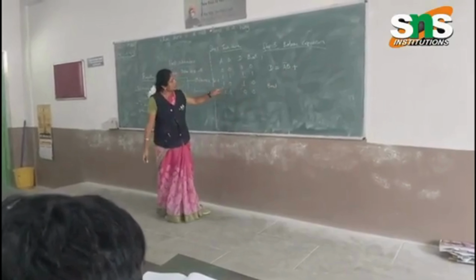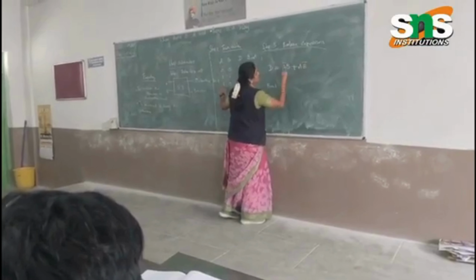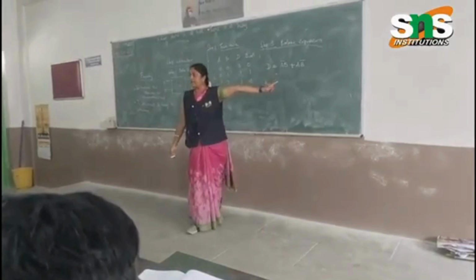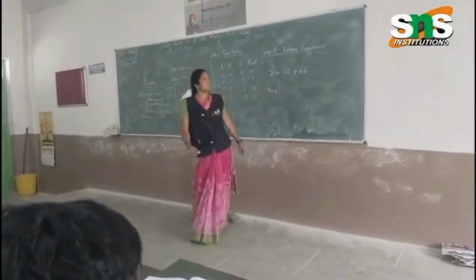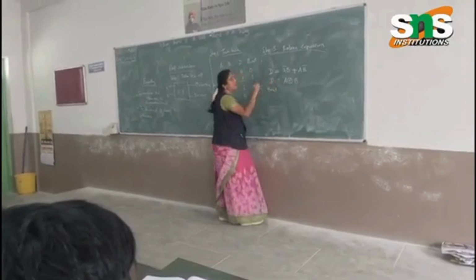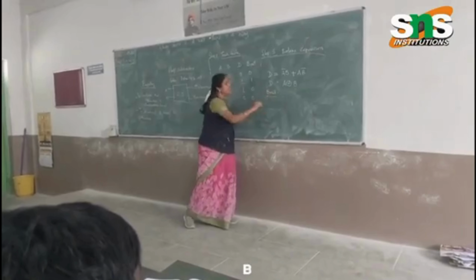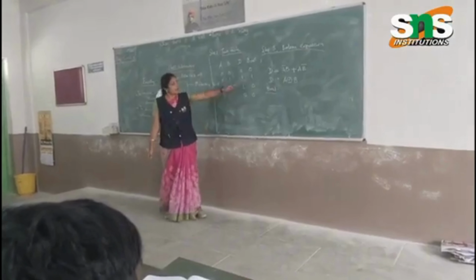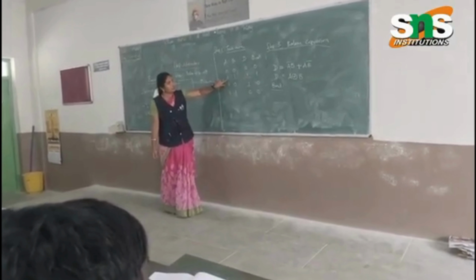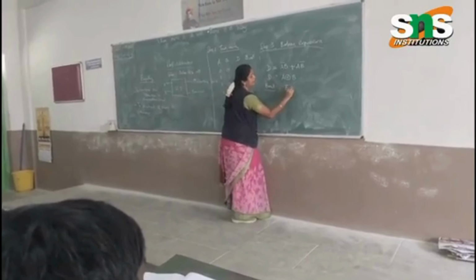It is in the form of an XOR gate, so we can write A XOR B. That is, the difference of the half subtractor is A XOR B. Next we have to take the borrow out. Only one output is high, so it is A bar B.